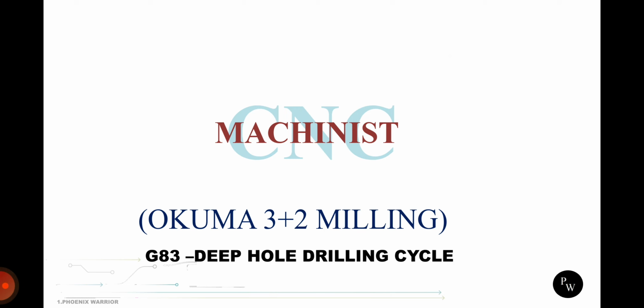If we are not able to give a peck, then in the absence of pecking, it will cause breakage of the tools due to improper chip removal from the hole. That's why we use the peck drilling cycle.